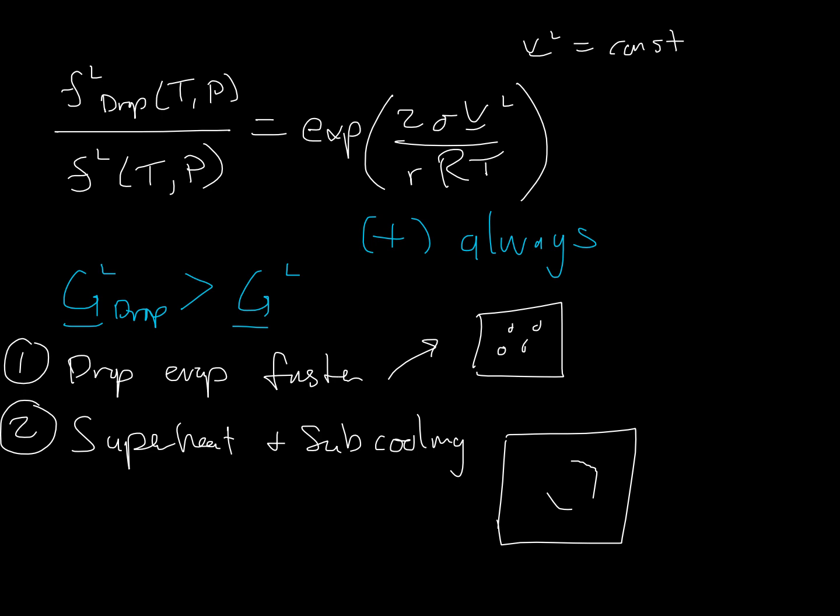So when you're boiling water on a stove top, a lot of times why it boils so readily is the imperfections in either the metal or you have dissolved gases in the water. So what happens is that water that's being jostled as you're pouring it from the tap has a lot of dissolved gases. Those dissolved gases will boil away or sort of evaporate before the water will, and they'll form little bubbles on your pan, and pots and pans. So that dissolved nitrogen, dissolved oxygen. And then the water vapor will nucleate onto those and then start to boil away. But the whole point here is that interfaces cost energy to form, and that causes superheating and subcooling.